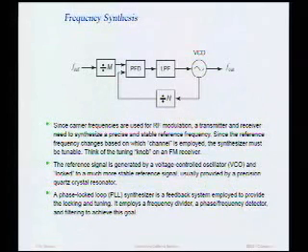As we'll see later on in this course, we can also build very nice phase modulators and frequency modulators by using something which is called a phase lock loop. And again, we're not going to go into the details in this lecture, but think of a phase lock loop as a system that takes this oscillator and locks it to this frequency, some multiple of this frequency. So for instance, this might be a gigahertz signal and this might be a 10 megahertz signal. And this loop is a feedback loop. It's a negative feedback loop that locks the high frequency signal to the low frequency signal.